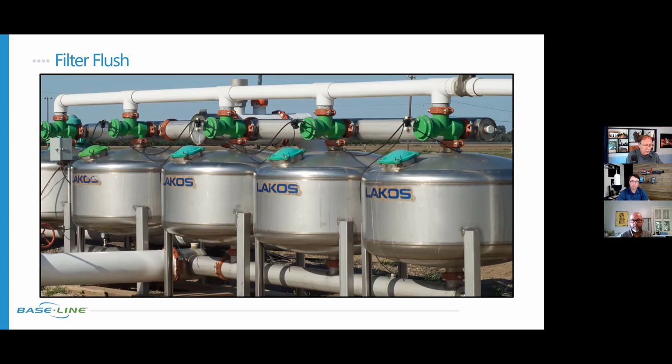What can happen there is the controller doesn't know when those flushes are happening because it happens when the timer says so. If it's connected to an old Intermatic timer or something less sophisticated, it's just going to click on and click off. What can happen is you can create an issue by your own doing, flushing the filters at the same time as you're running irrigation.